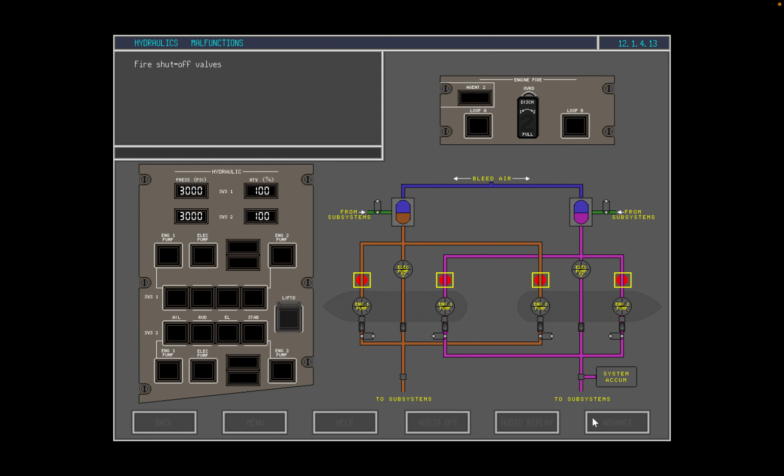Each hydraulic system incorporates a fire shut-off valve that prevents hydraulic fluid flow into the engine pumps in the event of an engine fire. If a fire handle is pulled, the associated dual fire shut-off valves close and terminate the flow of hydraulic fluid to the affected engine pumps. Hydraulic system operation remains unaffected. One pump per system operates from the remaining engine, providing sufficient hydraulic power to supply all System 1 and 2 consumers.